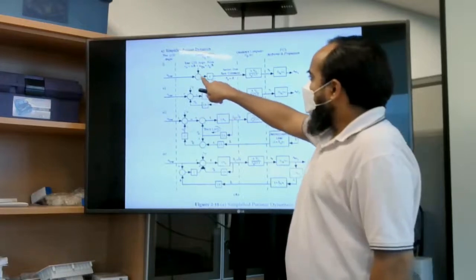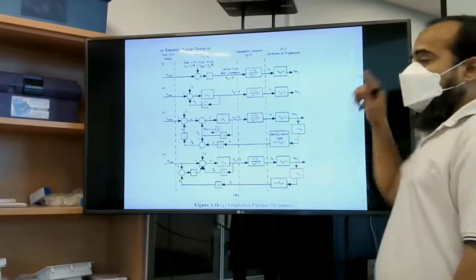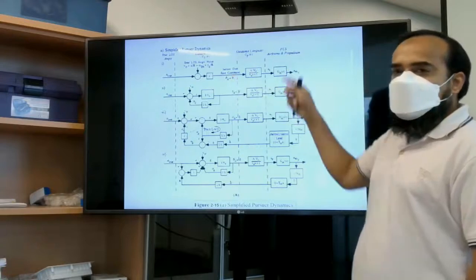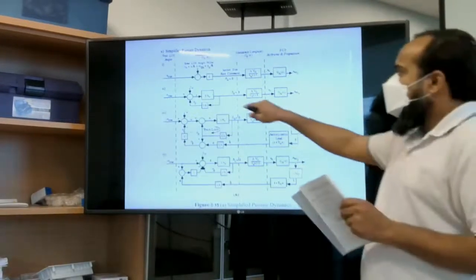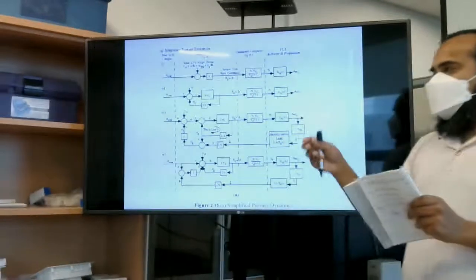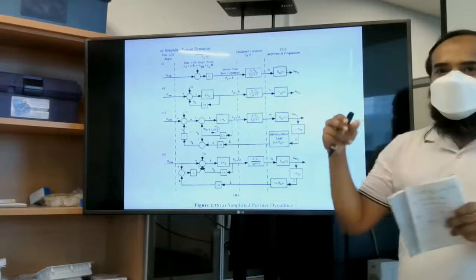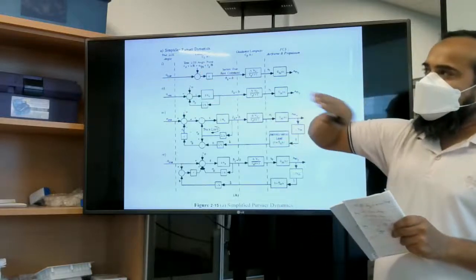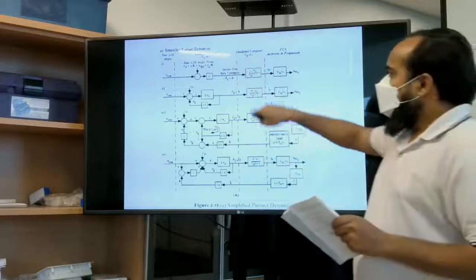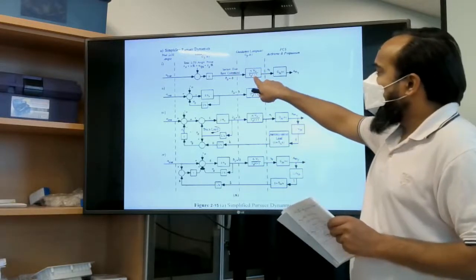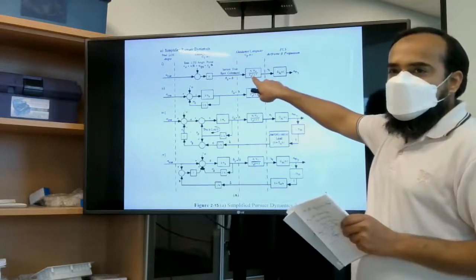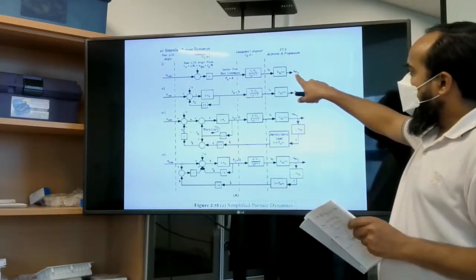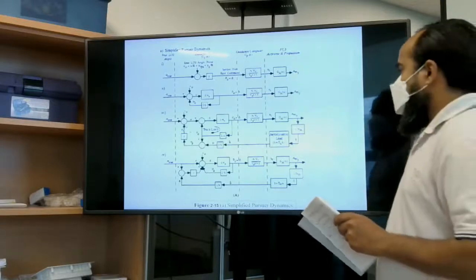Okay, then this is the inner angular system. Now without the radome effect, delta D is equal to the delta of the line of sight angle, because we consider the small time constant of the dish antenna, so that our dish focuses only towards the line of sight angle. So this is the guidance formula for the proportional navigation system, and this is the flight control system transfer function, which will give you the acceleration of the missile with respect to the Y axis. And similarly,